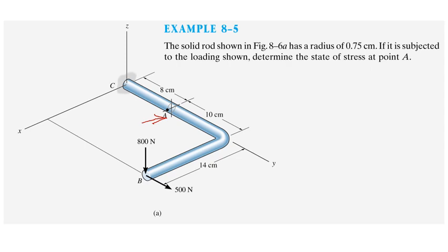Now there are two ways of doing it. You can use the free body diagram of the free end, from point A right until point B. Or you can also use the back portion, which is AC. You can use either one to determine your free body diagram. If you use point C, you will have something like that, not very good at drawing with this pad here. So that is point C, and over here you can then determine y, x, and also z. You can determine what the forces acting at that cross section are.